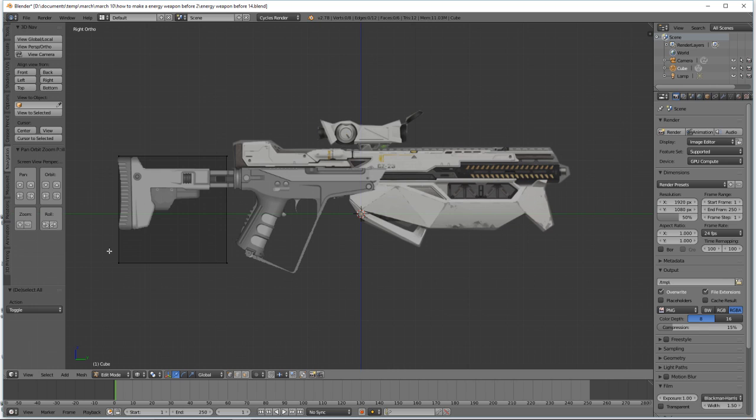However, when you're in this viewpoint, it looks like there's only 2. We go to wireframe so we can select not just what we see, but also the vertices that are out of view. So I'm going to hover my mouse here and press B for box select. I'll left click and drag to select what looks like 2 vertices but is actually 4, then take the manipulator and pull this up, matching this line right here.